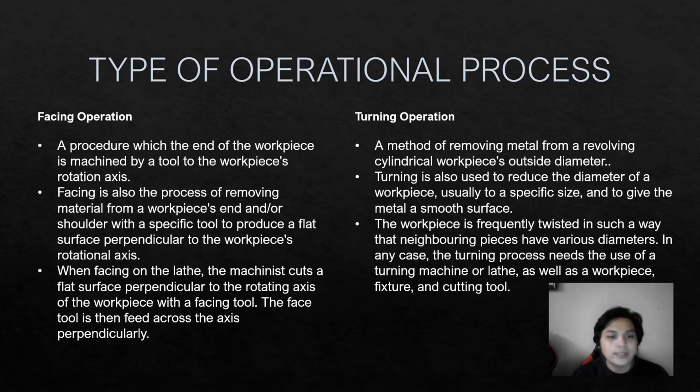So facing is also the process of removing material from a workpiece and/or shoulder with a specific tool to produce a flat surface perpendicular to the workpiece rotational axis. When facing on a lathe, the machinist cuts a flat surface perpendicular to the rotating axis of the workpiece with a facing tool. So this facing tool is then fed across the axis perpendicularly.